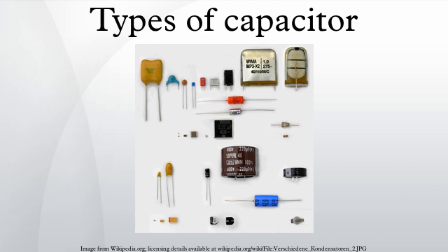Using a few thick layers of dielectric can support a high voltage, but low capacitance, while thin layers of dielectric produce a low breakdown voltage, but a higher capacitance. This assumes that neither the electrode surfaces nor the permittivity of the dielectric change with the voltage proof. A simple comparison with 2 existing capacitor series can show whether reality matches theory.